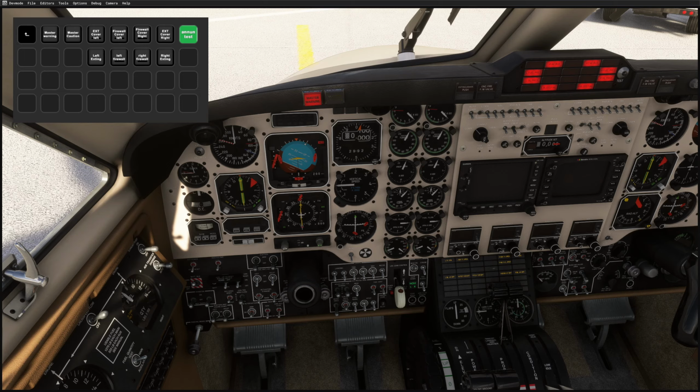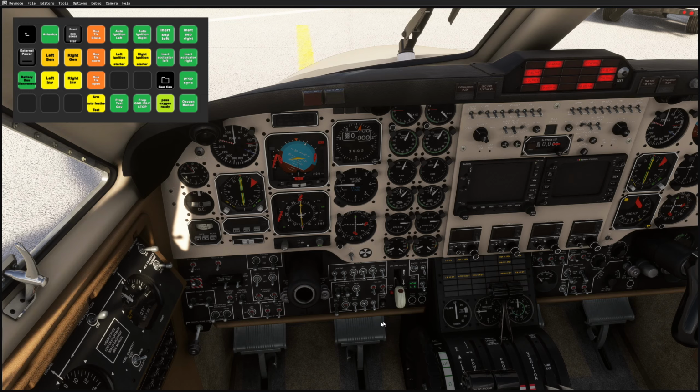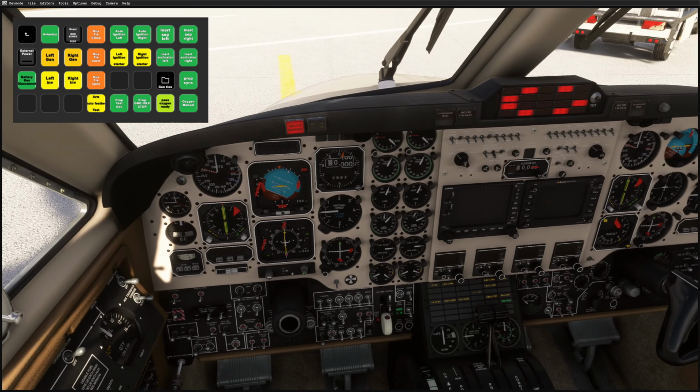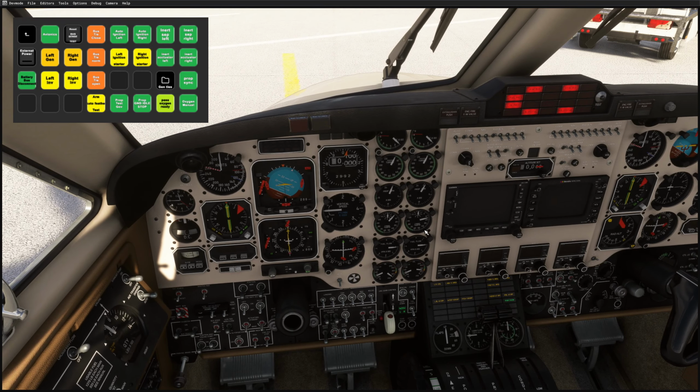So what we're going to do now is begin with the right starter. We start by pressing the right ignition starter, and then we will be checking that we're above 12% here. Once that's above 12%, we can introduce the fuel. So let's start that procedure. So we should see things turning over here. We can see that that's above 12%.